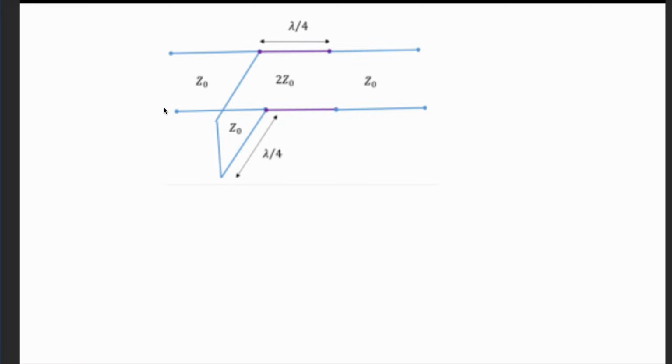It's like a section of transmission line, right? So in order to calculate the effective impedance, you need to use the formula of input impedance. Like what is the input impedance if I have a short circuit at a length lambda by 4? You can't directly write the impedances because it's a transmission line, and impedance actually varies across the length of the transmission line. Such a problem is there in the assignment also, but this is better than that. So if you can solve this, then you can solve assignment one also. I just want to know what your thought about it is.